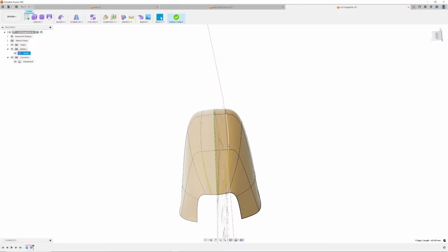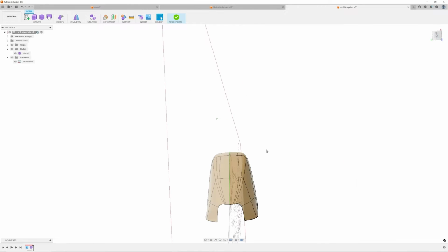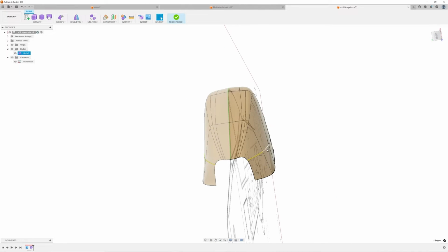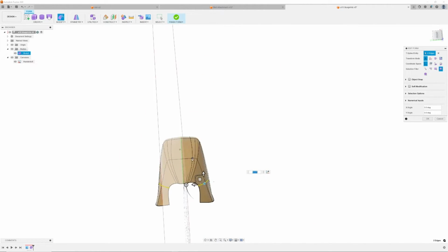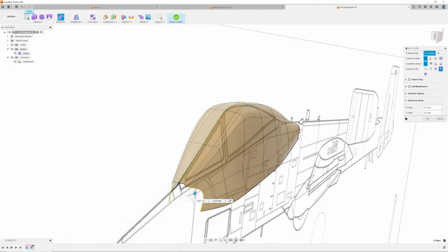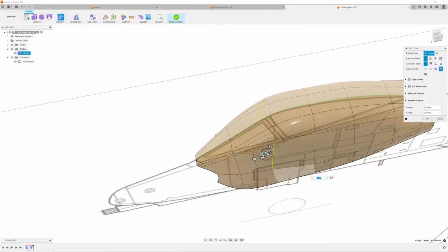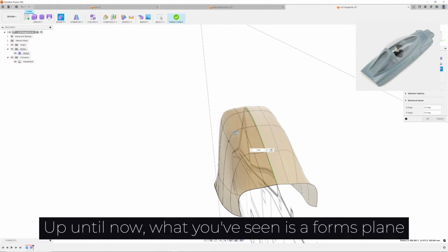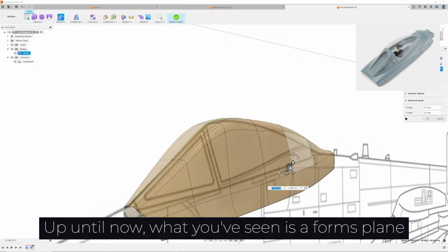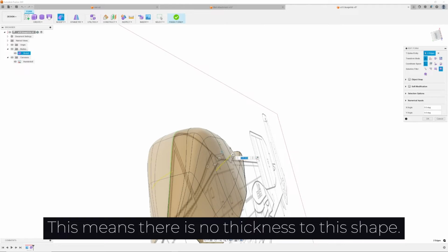Because I couldn't quite get the shape that I wanted with the original subdivisions, I add more edges onto the plane for finer shaping. You can find the Insert Edge command in the Modify menu at the top of the command ribbon. Notice the extra set of faces we added earlier are well below the drawn canopy lines from the plans. This is to ensure we mold the complete canopy. We will later cut and discard any excess. Take your time and make any adjustments you need. The shaping is the longest part of this process, and the more you do it, the easier it becomes.